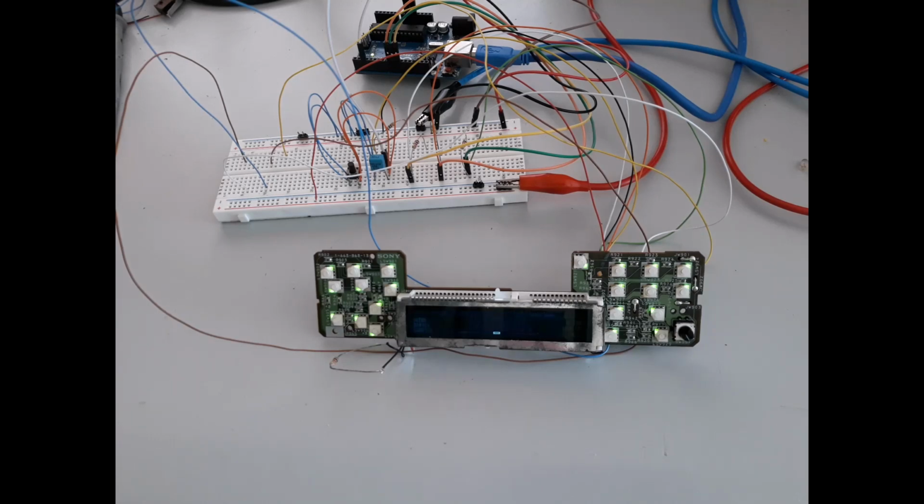There are 2 lines that collect the resistor values associated with the groups of buttons. Each side, the left side and the right side buttons, belongs to one line. We have to use one analog read pin for each one to recognize the pressing of the keys. It has one output associated with the rotary knob with 4 positions and 4 predefined resistor values for each position.